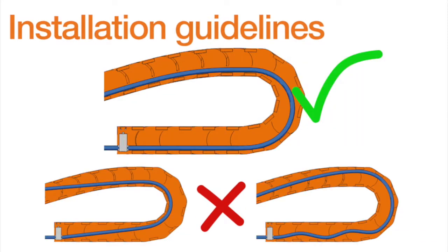So as I said before, we want to make sure that the cable is not too loose, but we also want to make sure it's not too tight. So the picture that we had seen the overhead of before was where the cable was too loose next to a cable that was properly strain relieved and installed. So the too loose cable is in that bottom right-hand picture where you can see it's along the outer radius. And what we're really looking for is the cable to rest in the neutral axis because we don't want it to be too tight along the inner radius that you can see in the bottom left-hand picture, or too loose, because if it's too loose, that could also lead to corkscrewing cables and other failure issues.